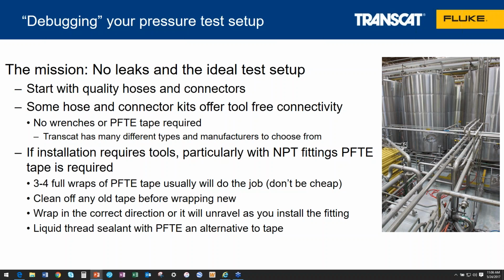So classic due diligence is to debug your test setup before you leave the shop. The mission, if you will, is no leaks and the ideal test setup once you get out to the field. So start with quality hoses and connectors. Okay, start with the connectors that you know are going to be reliable and offer repeatable performance.